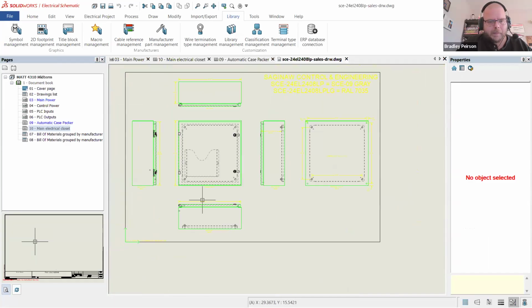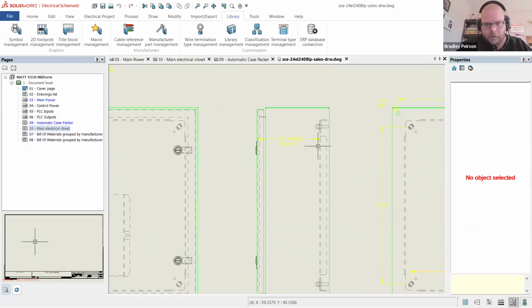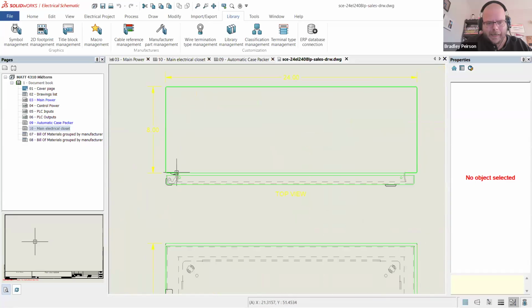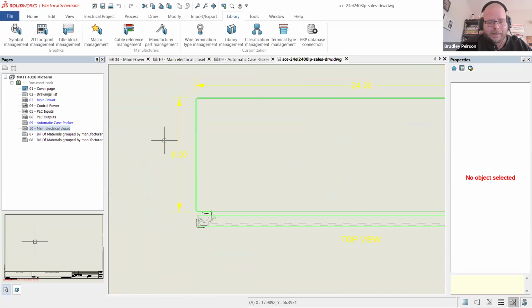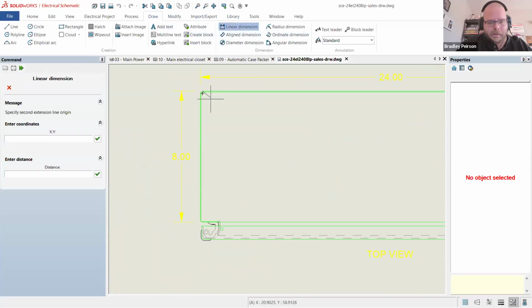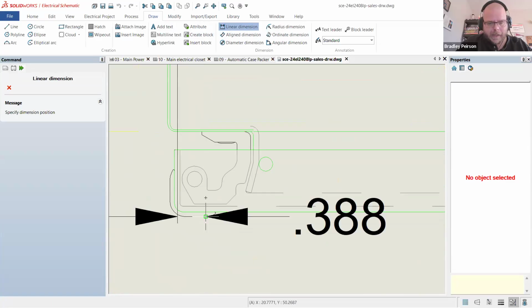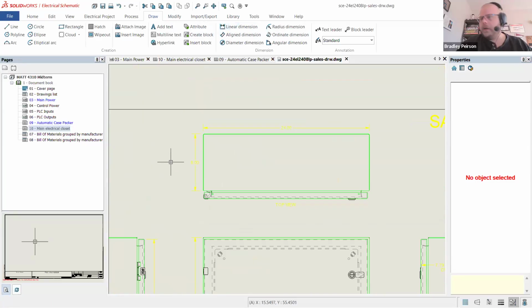What is the depth? All right. And depth is important, including the door. So this is not 8, it's 8 excluding the extra inch or so we get from the door. But remember, it'll be automatically scaled, and that scaling will include the door. So I need a clean dimension for that 8 inches. Let's just drop one in here and see. Again, high point to high point, 9.128 is going to be good enough. I'm going to do a quick metric conversion on my calculator because I'm not going to convert that in my head. 9.128, 25.4.